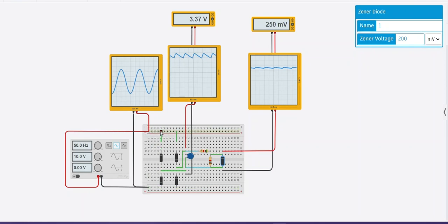So the flow goes first to diode 1 and diode 2 because they are in forward bias, so it moves to the resistor first and then the capacitor, and then to the Zener diode because it is in parallel. Then it goes back to our line here and moves to diode 4, and then goes back to the generator, the negative.